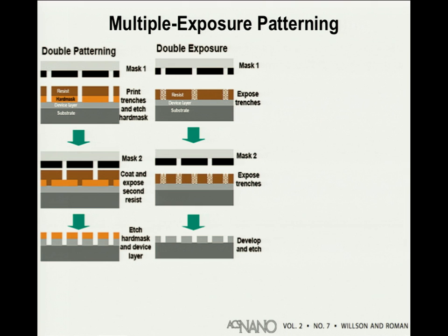So you expose once, then you get a new mask, and you expose the same photoresist film again. Again, the reason you couldn't use a mask that had all the features you wanted to begin with would be, again, because of diffraction. You would just get exposure everywhere. But between here and here, this photoresist film has the property that it could forget the sub-threshold exposure in the diffracted regions around the exposed regions. Does that make sense?